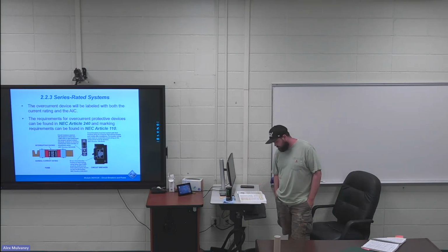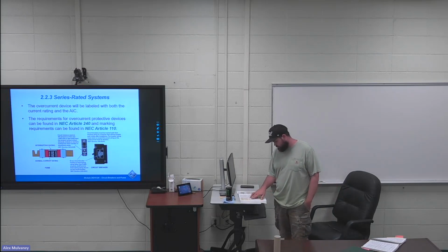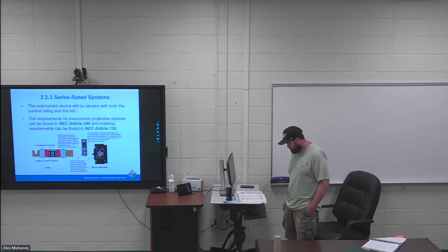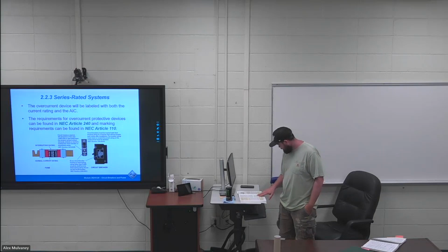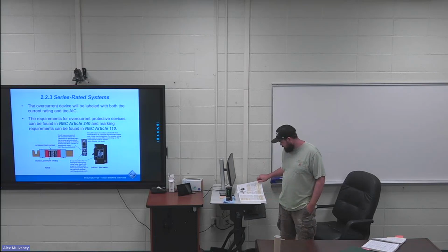The next paragraph, first sentence, is another online test question. For a 100 amp frame, current limiting circuit breakers, the threshold of current limitations occur in the range of 1,000 to 2,000 amps. Moving on from there, nothing else highlighted on page 10 or page 11. Flipping over to page 12.